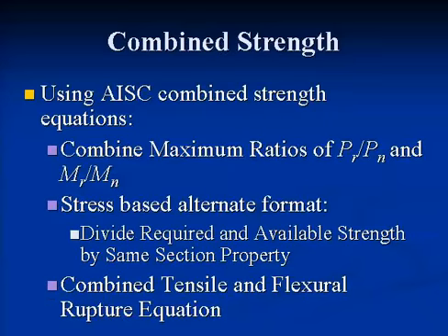The combined strength equations are right out of the spec, except for a combined tensile and flexural rupture equation. We noticed that the spec didn't really have anything adequate in that area. It's really not appropriate to be taking 8/9 of the moment when you're looking at rupture cases. Those interaction equations are not in any way based on that sort of scenario, so that's pretty much a P over A plus MC over I kind of interaction equation, and that has now made its way into the current draft of the specification. You'll be seeing that for all members.